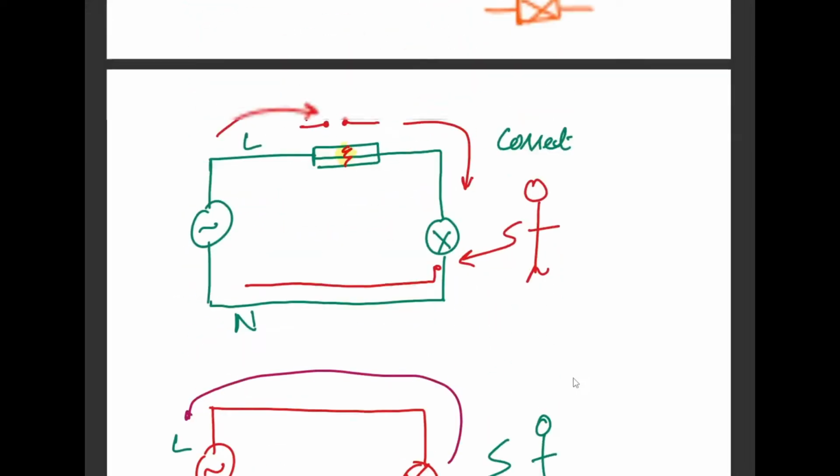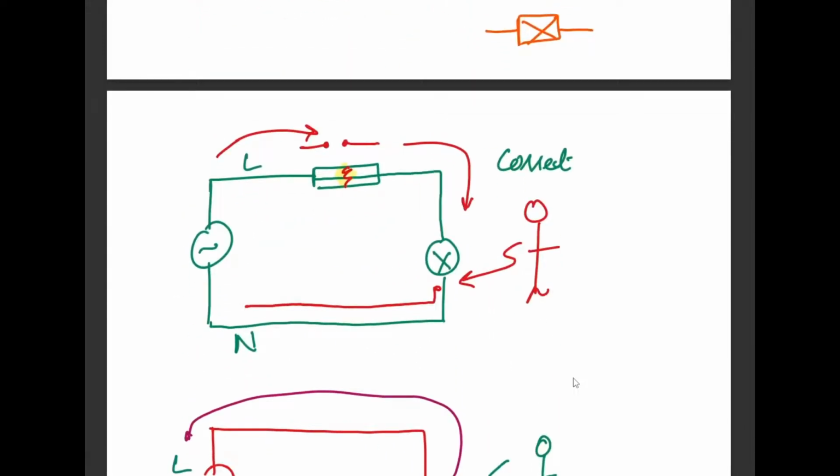Do we understand why we connect it in the live wire and not the neutral wire? Because the live wire would mean complete disconnection from the live wire, which has the high voltage. So the person who's coming to operate on the machine will always be carefree. He doesn't need to check the switch again and again, or check whether we're connected to the live again and again. He would just expect that he's safe to operate on this machine. Do we understand this point?